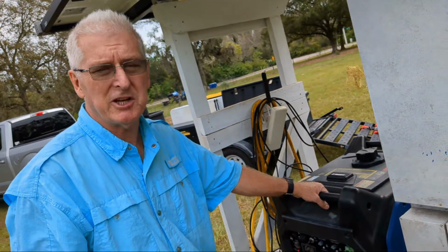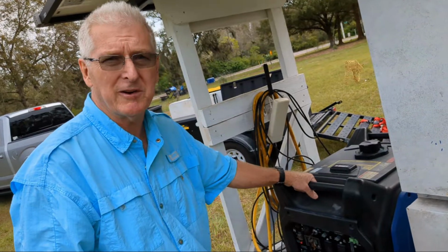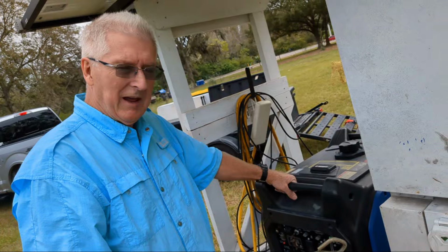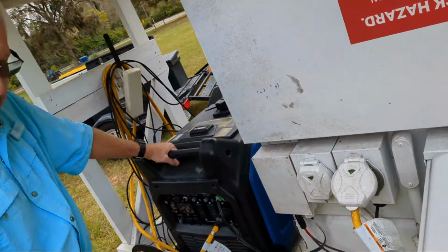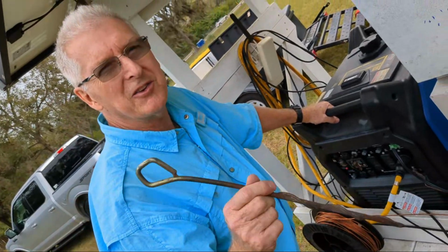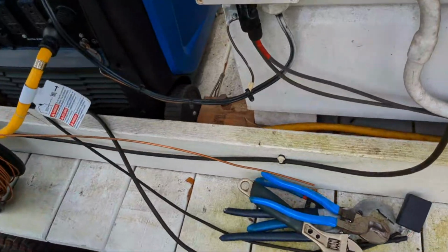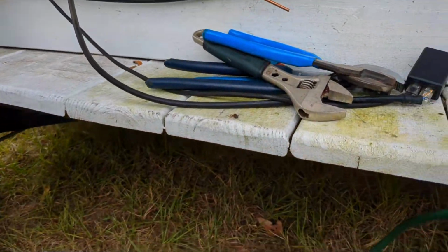It appears the generator is the reason for the ground fault, because our fault stopped as soon as we plugged the generator in. When I left here, we had a wire and a connection on this so we could connect a ground rod, and there is no ground rod here, and there's no wire left here anymore either. What is that? Where was that? It was probably laying here, and it might have slid underneath here.